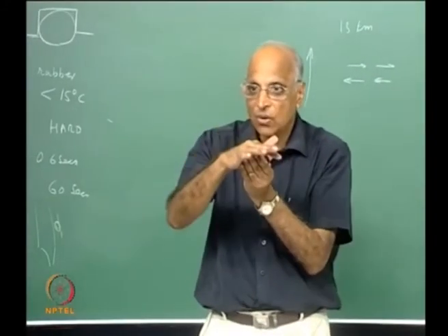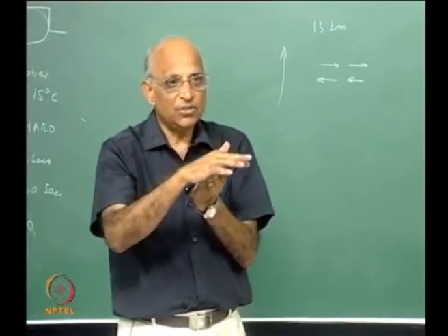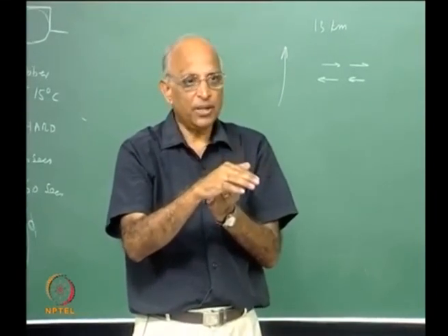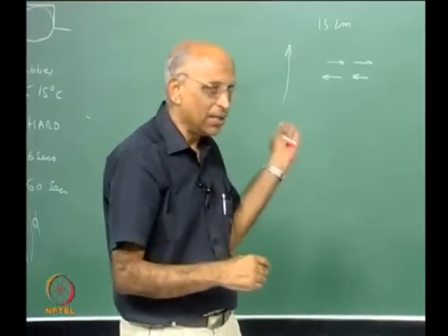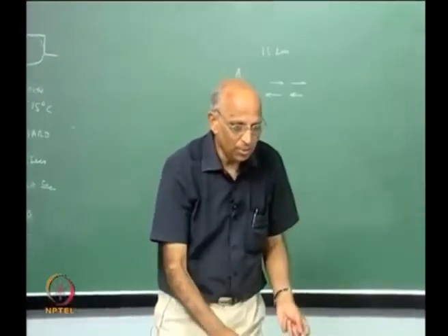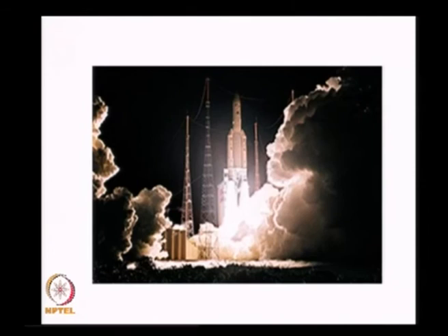Therefore, we do see the corrective action of aluminum oxide in sealing the hole. In fact, one of the recommendations is, whenever you use an igniter for pyrogen, we never put aluminum because the nozzle will get clogged. But here it helped, but the failure was because of the O-rings which were not doing the job well. Well, this is about the space shuttle.